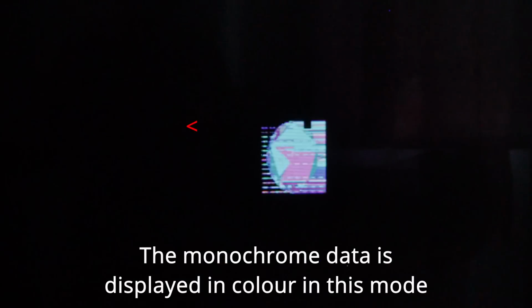I've been at this for hours now, and it's still difficult to find options to put in the bits in the registers that actually work together properly. For example, I discovered that to do area fill, you have to have the source image in monochrome, or so it seems, like I had originally with 8514/A. And monochrome images are very small, they're just 1 bit per pixel. So that means that you can't see it anymore, or at least those flashing dots are the source image. And it's repeated 8 times because of the problem I mentioned earlier with the map width. In order to fix that, I'd have to have the map width 8 times bigger than the width of the screen, but you can't use a number that high.